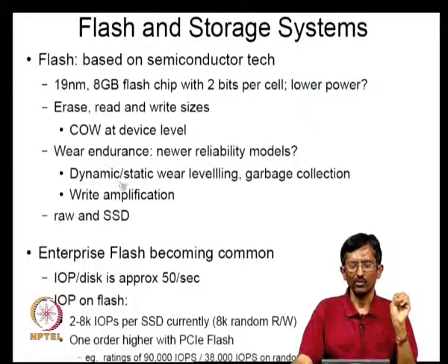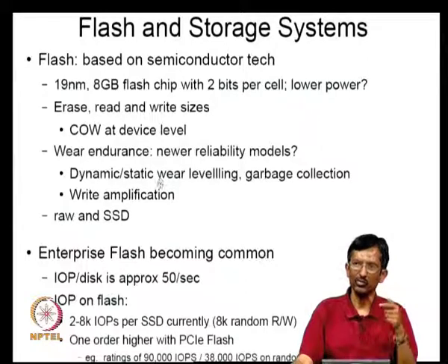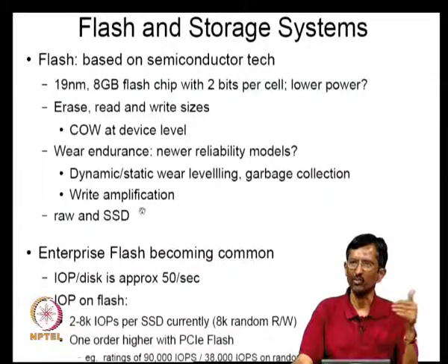And so, the issue about this is that any time you do any wear leveling, you are also introducing new writes. So, there is something called write amplification that goes on. That is, for every write, possibly some other writes will come into the picture later, because you want to do the leveling. So, this write amplification is an issue. You want to make sure that this does not become big.